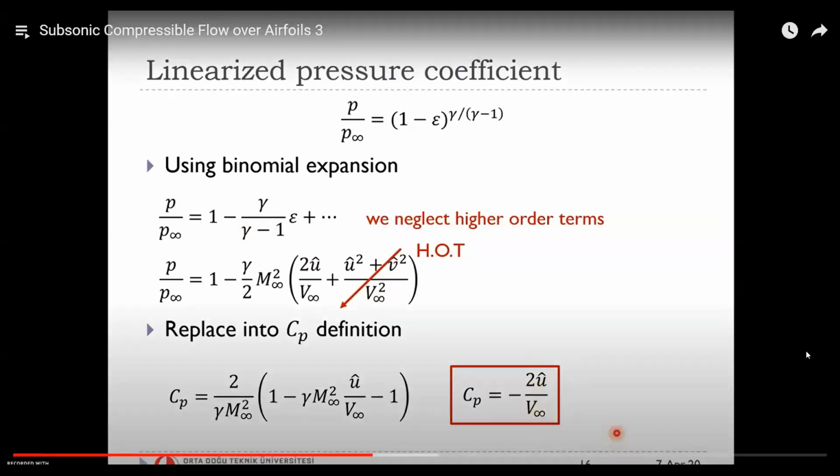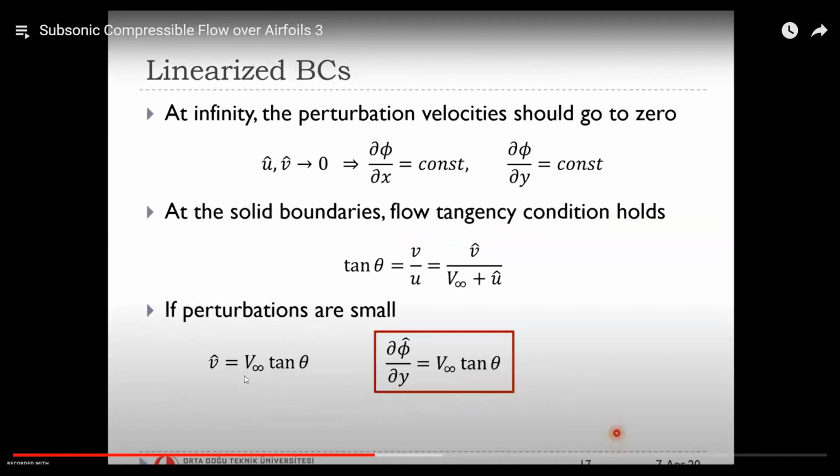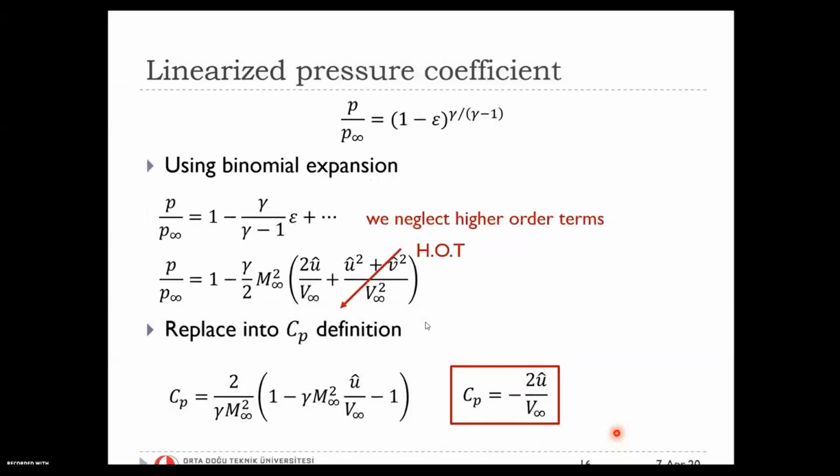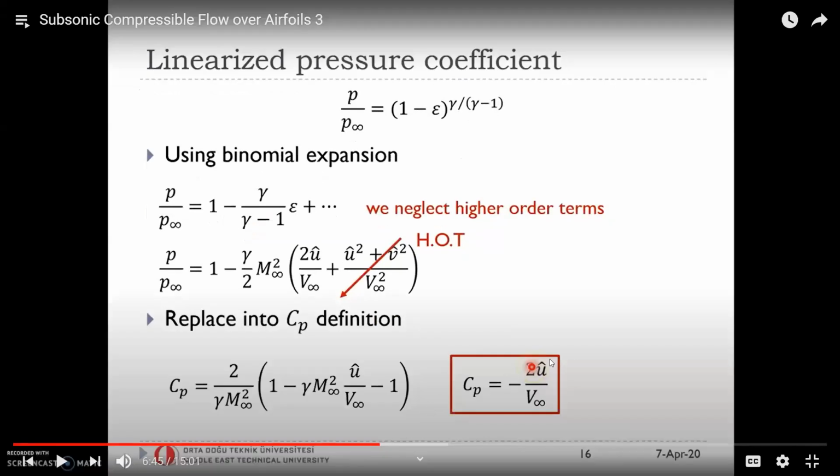Okay, I think it's a good point to stop here. As you have seen, for the linearized theory we obtained first of all a governing equation, and also a simple relation for the pressure coefficient on the body, on the thin airfoil, written in terms of the perturbation velocity along x.